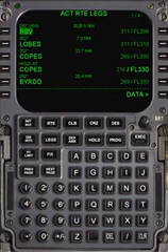Inertial reference systems (IRS) use ring laser gyros and accelerometers in order to calculate the aircraft position. They are highly accurate and independent of outside sources. Airliners use the weighted average of 3 independent IRS to determine the triple mixed IRS position. The FMS constantly crosschecks the various sensors and determines a single aircraft position and accuracy.